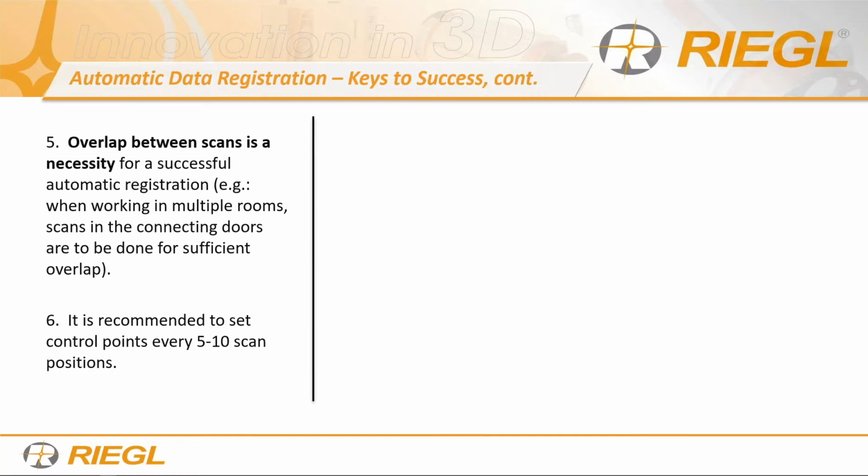Maybe another webinar I can do is best practice to plan a project, right? I'll have some scenarios where we go indoor, outdoor, linear projects, large projects, open field projects. I could do a map on how I would particularly set up these control points versus scan positions, kind of like planning a project. But yes, it is recommended to use control not only at the beginning and the end, but also in between. And it's all up to the user to define these control points and where to put them.